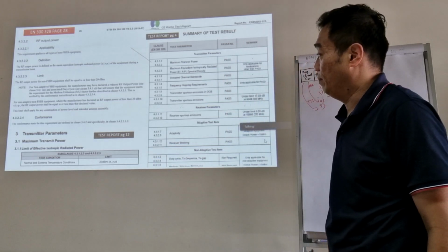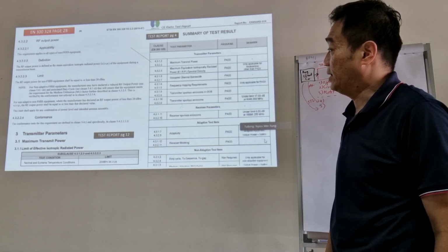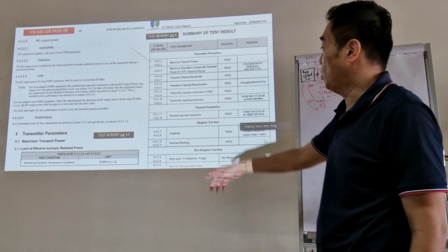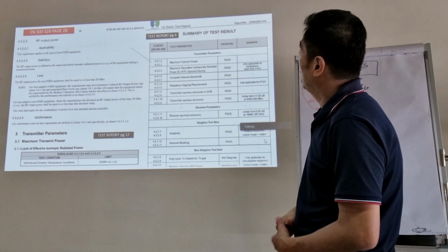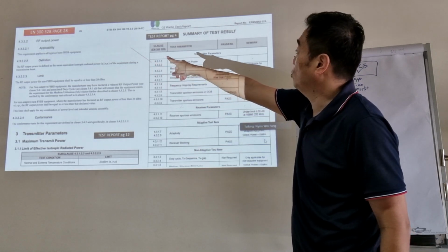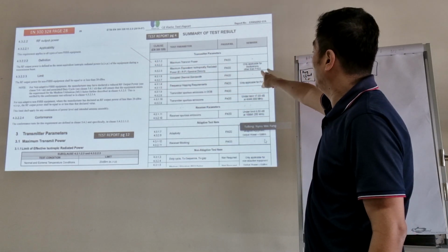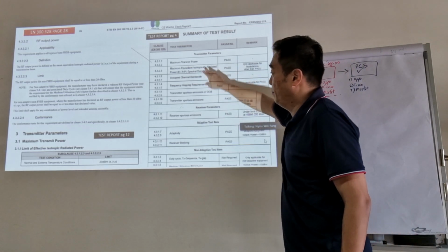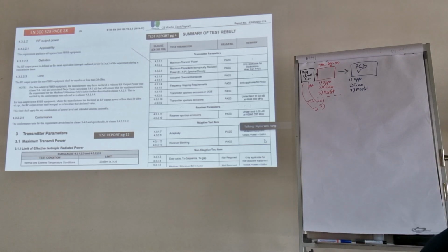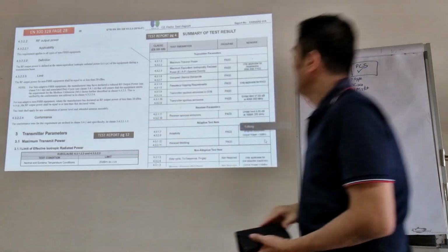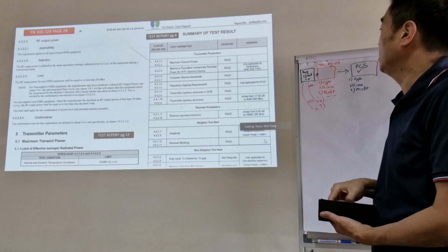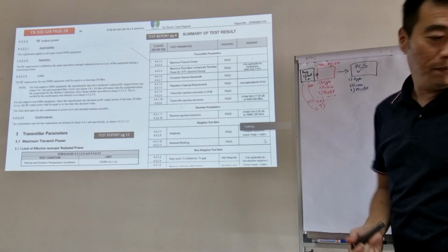The limit is 20 dBm. Right? Okay, for the maximum transmit power. Which page is it in the test report? Page 4. What do you see? It will coincide. 32, then you check the 32 one. Okay, all of these pass, right? Maximum. Can you see? Do you see the result versus the requirement? This is the same as this. Okay? Then its result passes. Right? Okay, correct.